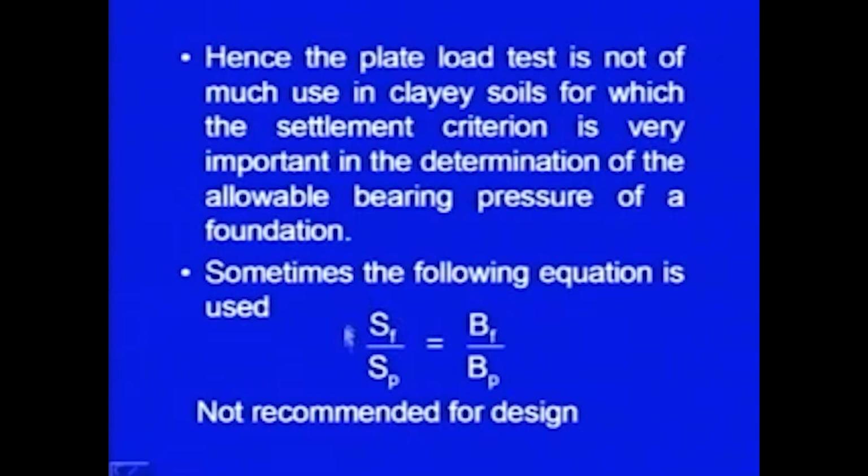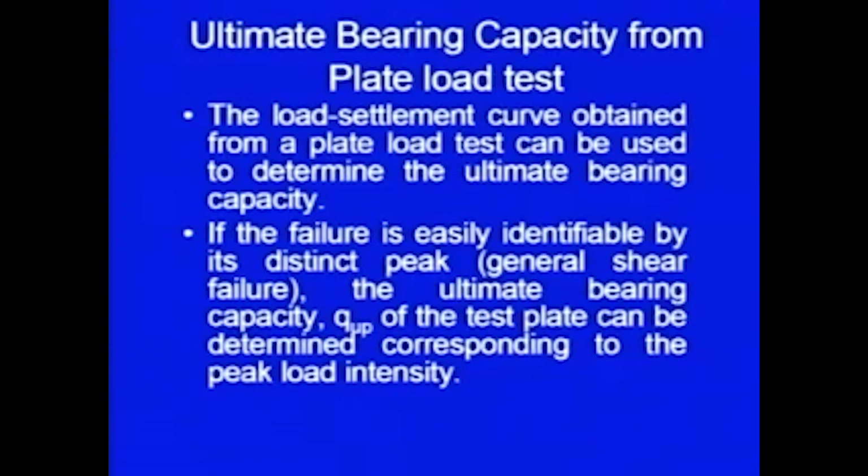Sometimes people use one correlation, SF upon SP is equal to BF upon BP. This particular correlation, which is sometimes used, is not recommended for design. So as far as the plate load test is concerned, it is not of much use for cohesive soils.